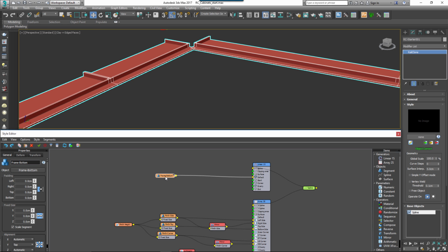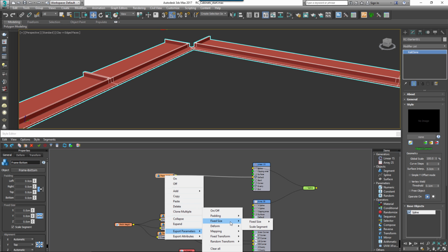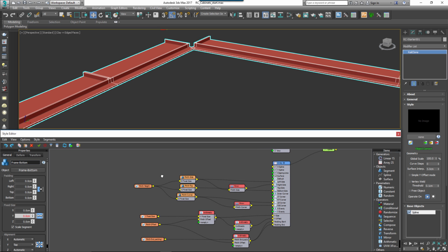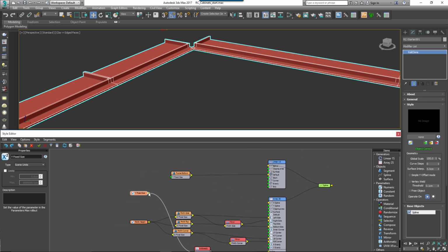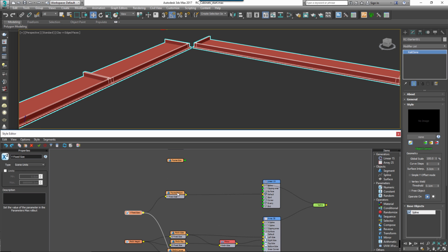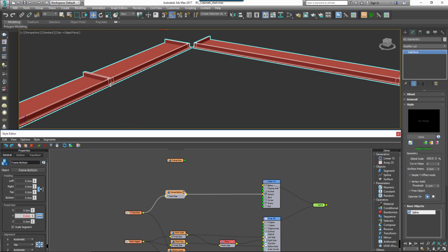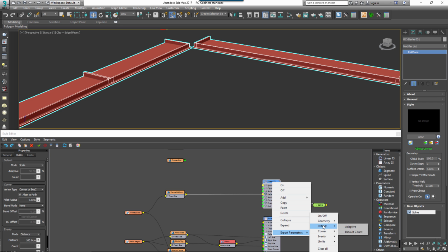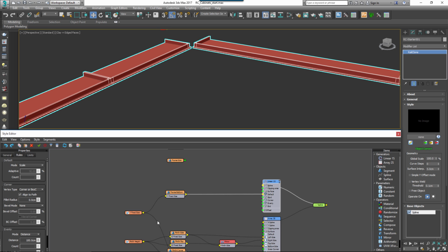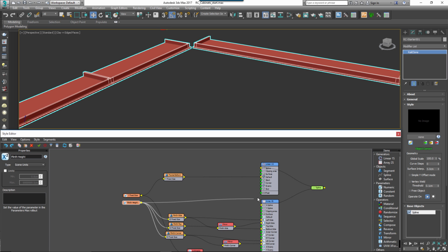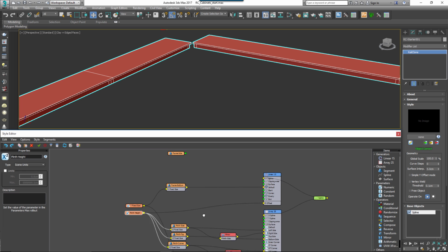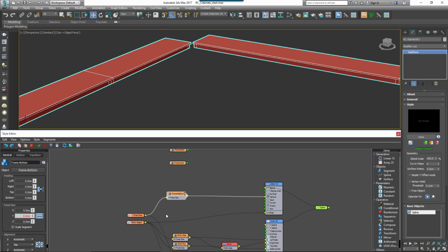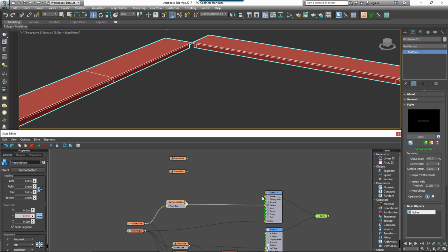And we want to adjust the depth of this cabinet, so export the Y fixed size property of this segment and connect the Y fixed size numeric node that's already in the graph. And then finally, the cabinet bottom is currently sat on the floor intersecting the plinth, and we want it sat on top. So to do this, we need to adjust the Z offset parameter of the generator. So right click on the generator and export the Z offset parameter, and then wire the plinth height numeric node to the Z offset input. And now, as you can see, if you adjust the height of the plinth, the cabinet bottom also moves up accordingly. So with the bottom side done, we can add the back and the sides of the cabinets.